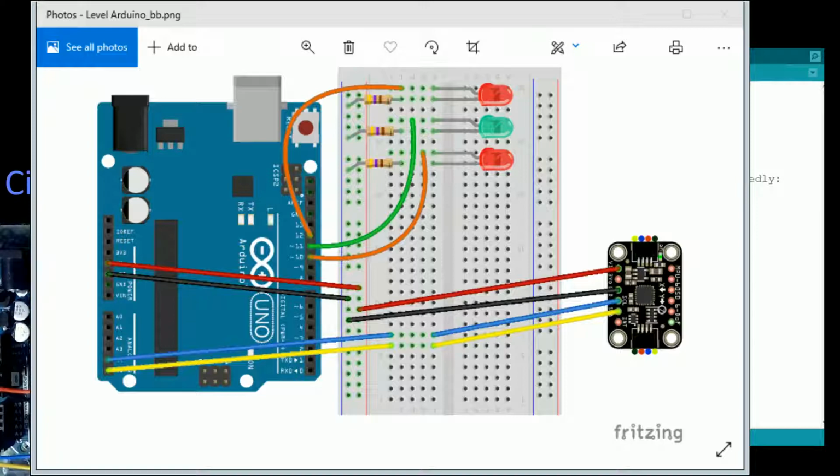And it's pretty simple. It's just power and ground, and this will take 5 volts or 3 volts, so it doesn't matter which board you're using. The same interface board will work with both. In fact, we're going to take this same board and move it on to the CircuitPython version later. And it's just a communication line, and that brings in everything that's inside of this thing, which does way more than what we're going to use it for.